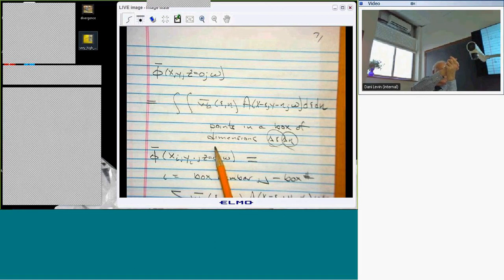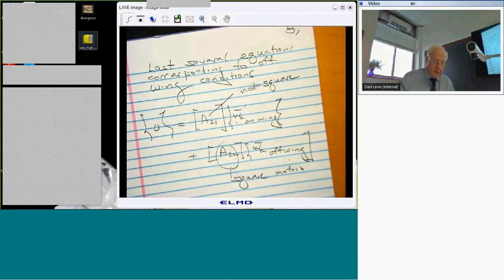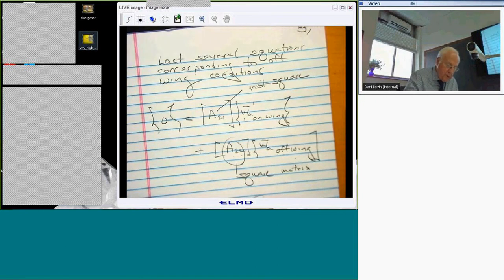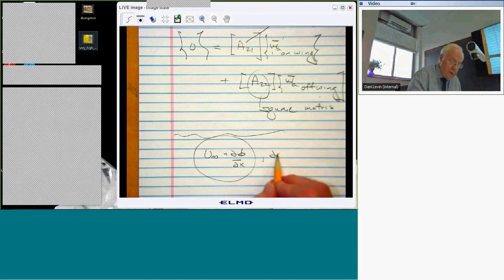Is that fair enough? I thought we were saying that was like the whole flow velocity. That didn't make sense. No. The whole, obviously, mostly being the x direction. No. The whole velocity is U infinity plus dphi/dx. So this is a perturbation, right? That's the component in the x direction. The component in the y direction is this, and the component in the z direction is that. So if I want to know the total velocity, I square each of these and take the square root. That'd be the total magnitude of the flow velocity.